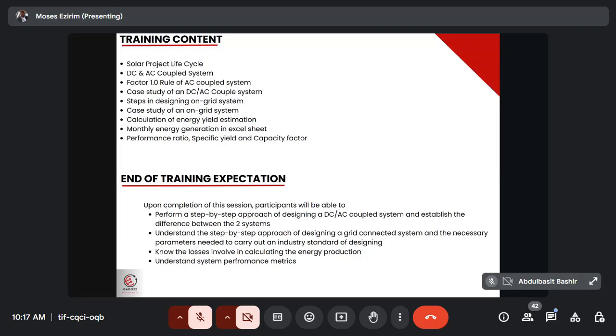Whichever way, by the time you are able to finish your logging and analyze the data, you'll be able to identify the trends and know what is going on with the load profile of the client. Then the next thing is to identify the space, if it is ground mount or roof mount. If it is ground mount, you just need to identify the area that you want to put the panel, and tell the client which area he is allocating for the installation.